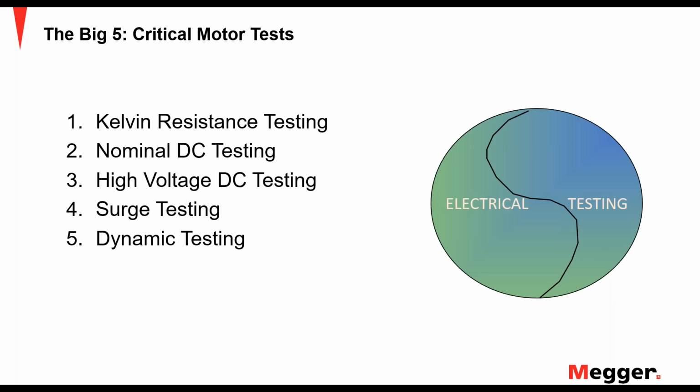And then the 5th is to throw in dynamic testing to evaluate the environment that motor is living in, to evaluate the power that we're giving it. What kind of quality of power are we giving that motor? And to look at the load affecting the motor, and how the motor is responding to that. That gives us an insight into the environment that motor is operating in.